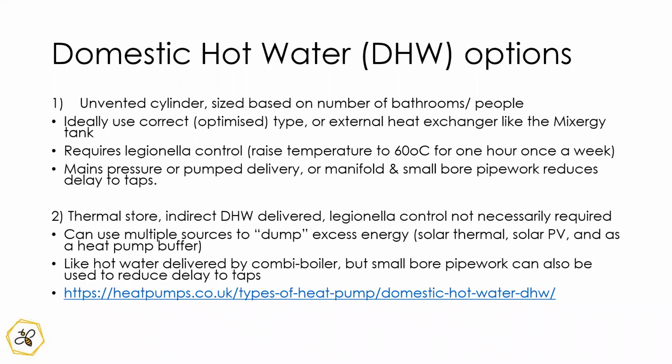With a heat pump, you would ideally use the correct type, optimized for low temperatures going through. The Mixergy tank has an external plate heat exchanger, which is quite neat. We're not really advocating keeping your hot water at 60 degrees the whole time, which is what domestic hot water cylinders are generally designed to do.